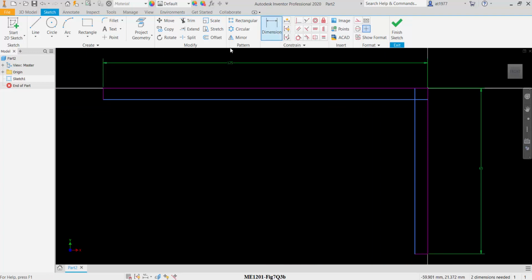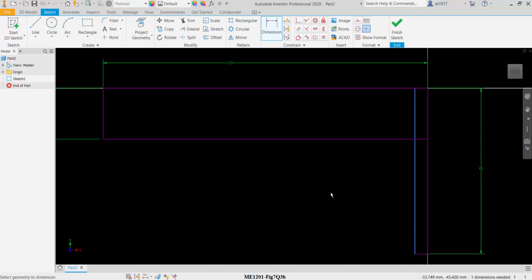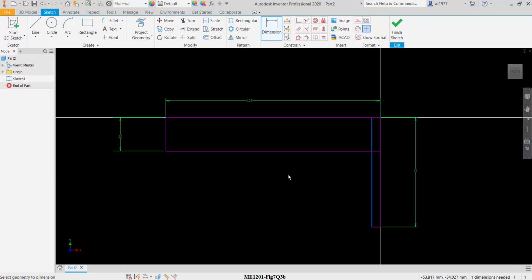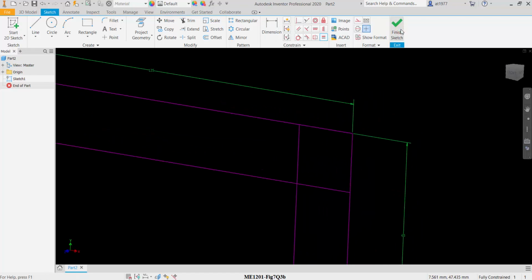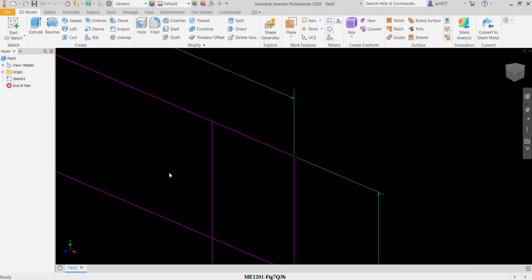to zoom extend. Next, dimension the size to be 20. And I want the bottom, the thickness to be the same as here. I can put equal, this to this. Once done, finish sketch, or you can press the shortcut key E followed by the extrude command.